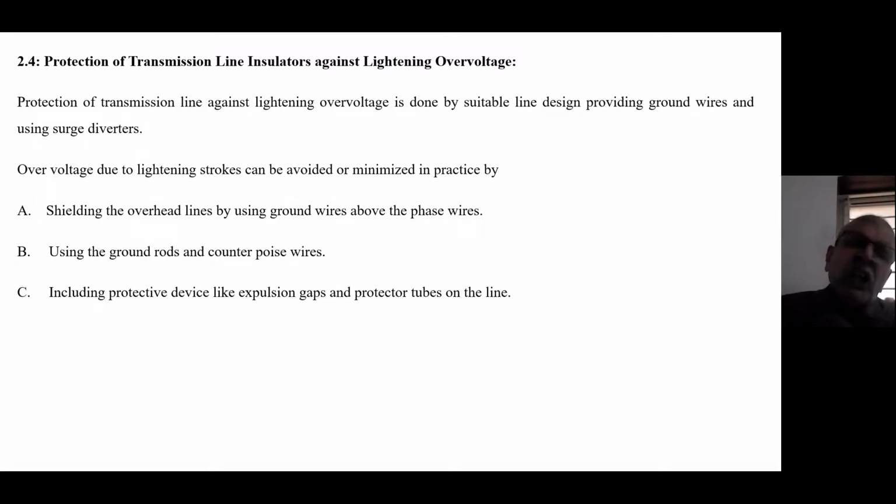That top wire, running continuously from one end to the other, is for protection against lightning or voltages. But that conductor is connected to the iron tower. Iron is not a very good conductor of electricity. So that ground wire has to be connected to pakka ground.